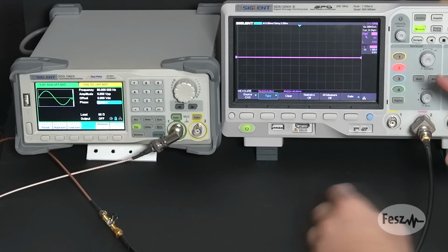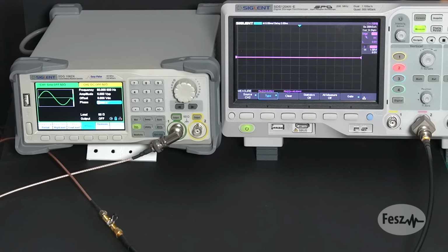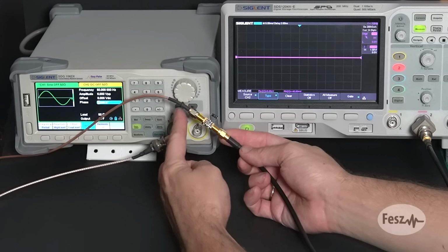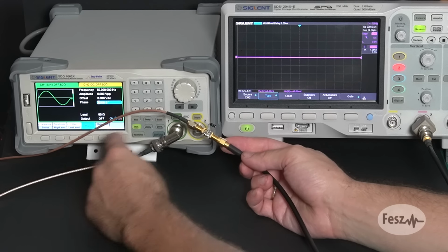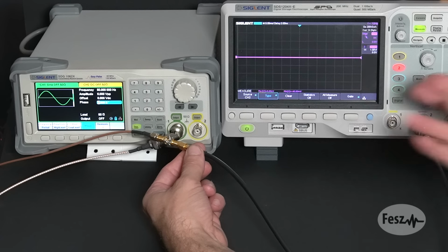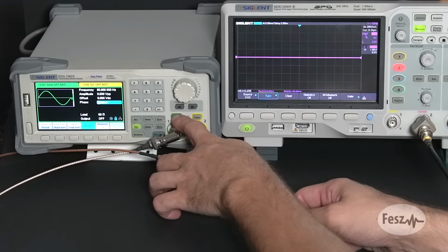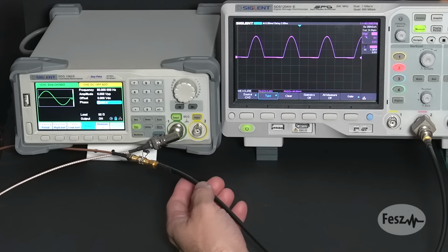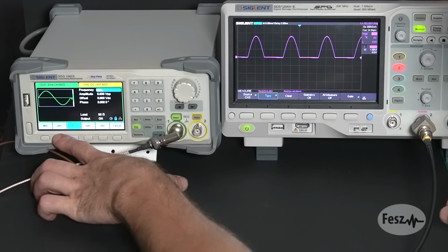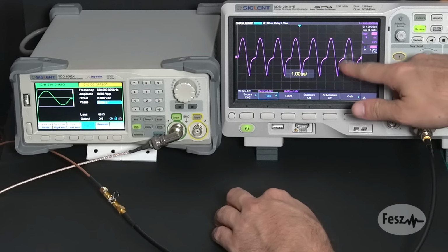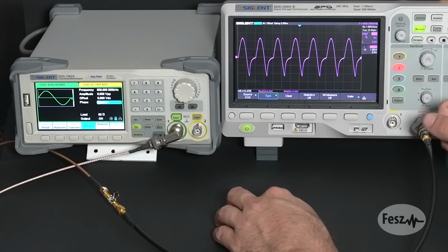Now, just to validate this behavior, I will also try out this experiment in real life. What I have here is a 1N4004 diode placed in series between two SMA connectors connected to a signal generator on one side and the oscilloscope with a 50 ohm termination on the other. If we apply a low frequency signal with zero DC bias, the diode is blocking as expected. But when we move to high frequency signals, we see the reverse conduction effect appearing, which does not keep the diode fully conducting during a sine wave period.